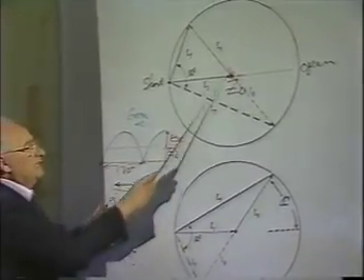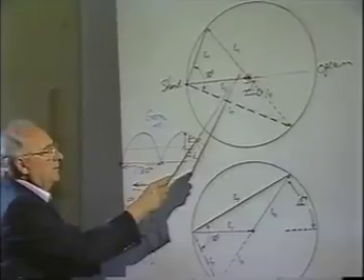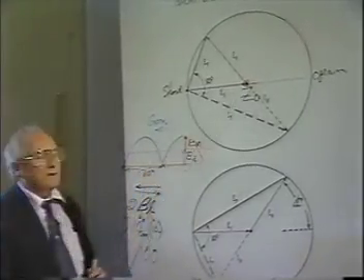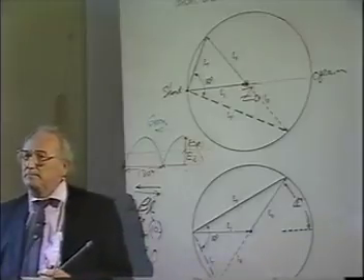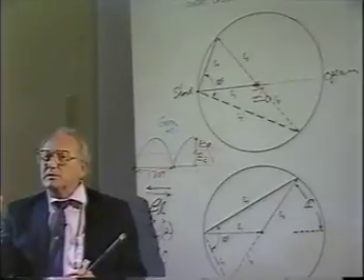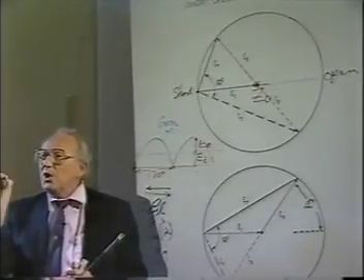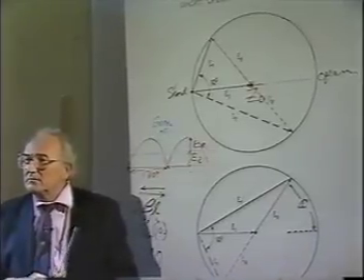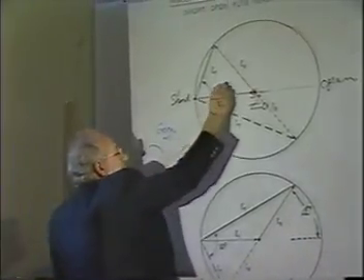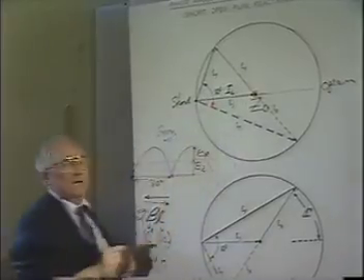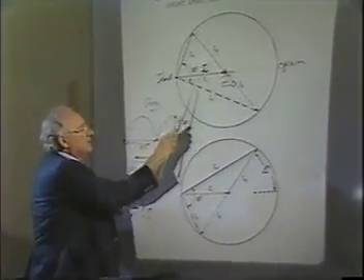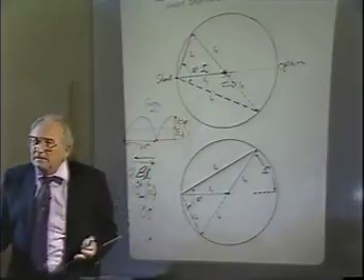Now notice, if E sub R is 0, this is not here. Nothing here. E sub R is 0. This puts you at the center of the chart. The only thing you would have is E sub I. If you have E sub I traveling on the transmission line, must there also be a current? What do you call that current? I sub I. This vector then, right here, represents E sub I and I sub I.